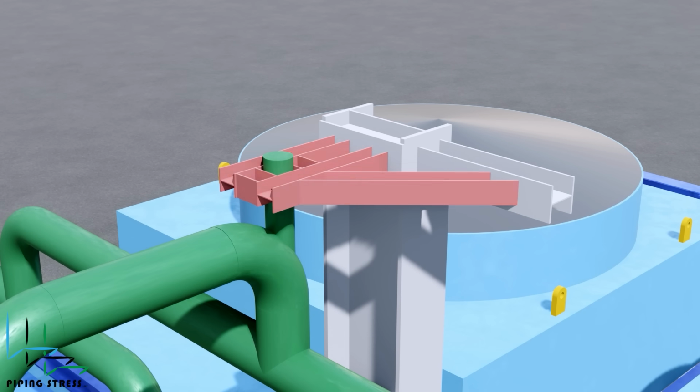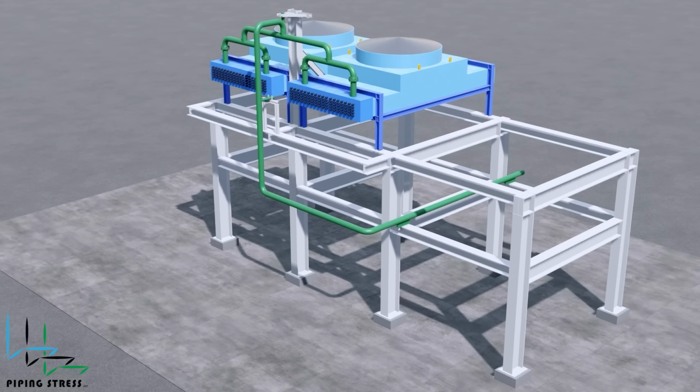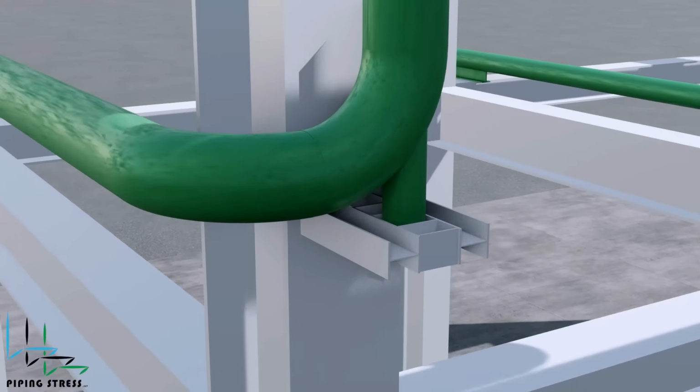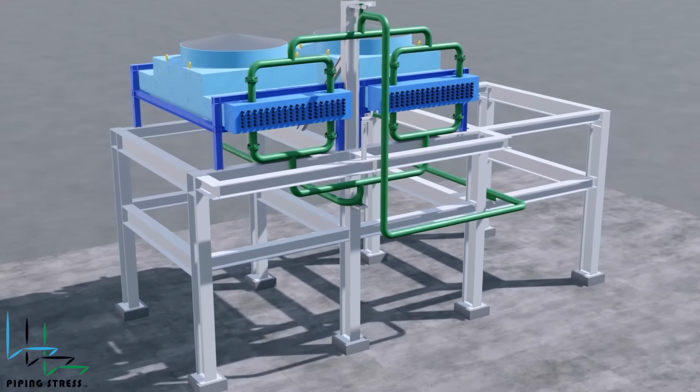The other vertical trunnion is guided in both directions. The reason for this is keeping the main line in the middle of both air coolers before cascading. This will also help the symmetrical piping approach for air coolers. Piping designers prefer symmetrical designs for air coolers to ensure even fluid distribution. Examining the outlet piping, the same principle has been applied to the support structures. The vertical trunnion holds the cascaded piping at the center of the air coolers.